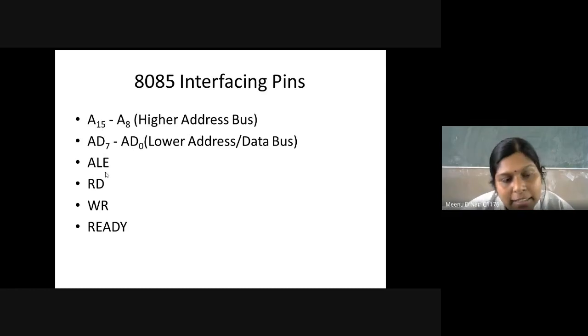Then ALE is address latch enable. RD is the read command signal. WR is the write command signal. Then READY indicates whether the CPU or processor is ready or not. These are the interfacing signals in your 8085.